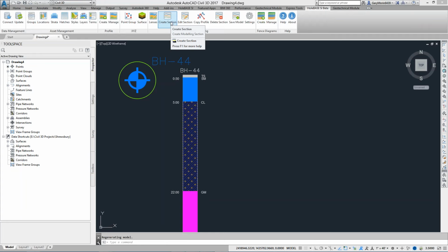Then on top of that, we're also building tools to generate sort of lenses and outcrops of geology really rapidly. You just draw the extents of the geology, click on it, tell it which geology it's supposed to be, and it actually does all the work you saw me do before with feature lines and break lines. It does it all automatically.